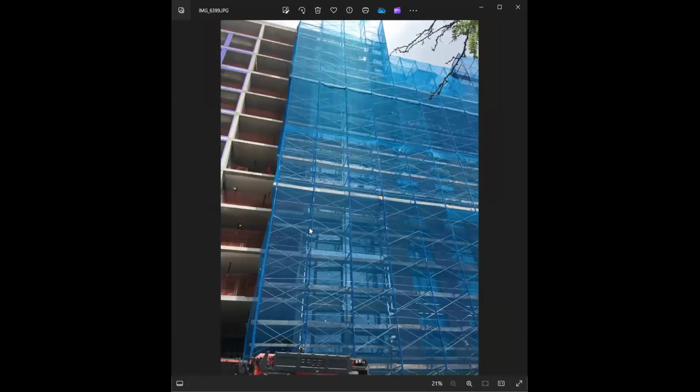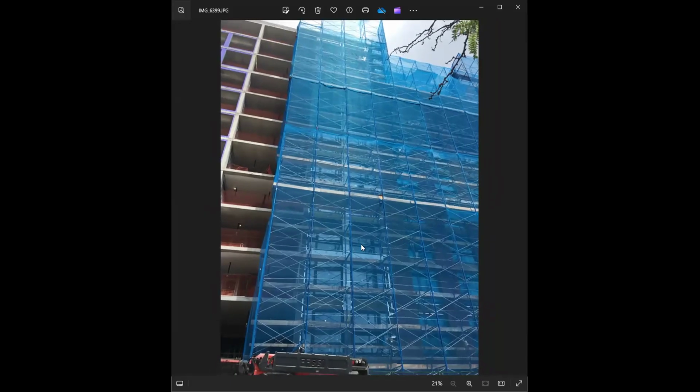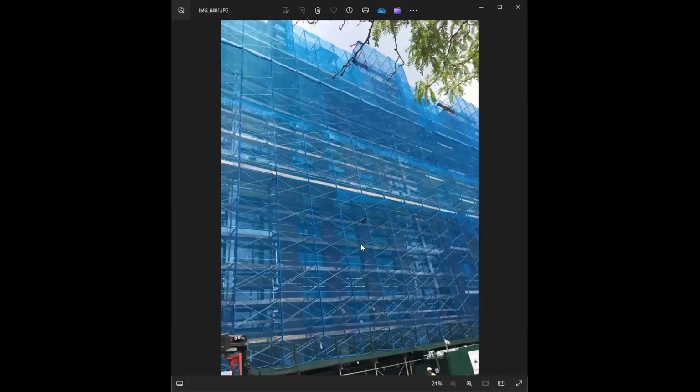So now there's the installation of the wall, the details. It's the passage wall. So they're going to put the waterproofing first, then they're going to attach the insulation, and after that they're going to attach the masonry bricks. This is the building that is currently under construction.